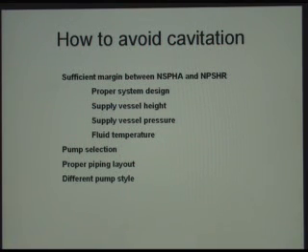If you're talking about a different kind of pump, like a positive displacement pump, are you very concerned with NPSH? We're not so concerned with NPSH because you don't have a continuous potential for vapor formation, but we are concerned with an acceleration-deceleration head because of the pulsation that reciprocating pumps put into the pumpage. You have a situation where you don't have a nice continuous flow into the pump. It's going to pull stuff, and then it's going to stop, so you have this massive fluid suddenly accelerating as the piston pulls it in, and then it stops when the piston stops.